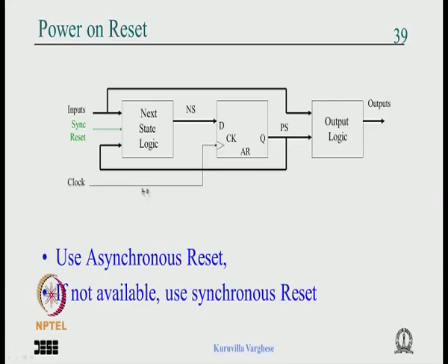So the maximum clock, you must be already getting the idea, it has something to do with the delay of the flip flop and the delay of this logic, and we have already seen the maximum frequency of the state machine, which is nothing but the maximum frequency of a data path or a register to register path.